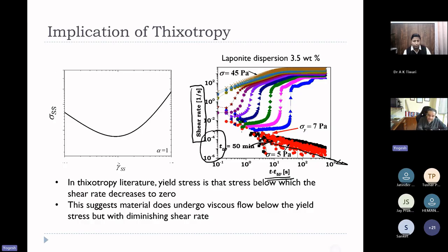All right. When it is below a certain shear rate, but when you apply that particular stress to be above a certain threshold, then it shows a sudden increase in shear rate. So below a threshold of stress, you see material flow ceases. The shear rate gets induced, but that shear rate goes on continuously decreasing. Eventually, it leads to stoppage of flow, while above that particular threshold, it flows and eventually flows with a constant rate. All right. So this behavior is a very peculiar behavior.